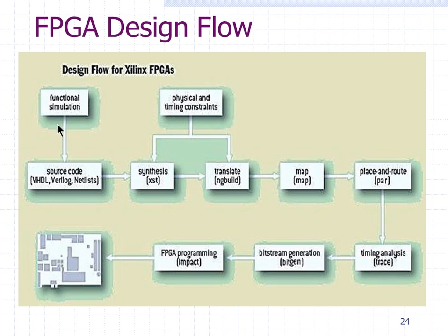If it is not correct, it's an iterative process. You keep changing the design or the test bench till you get a simulation result which matches the design specification. At that point, you say my design is functionally verified. Functionally verified means it matches my design specification.